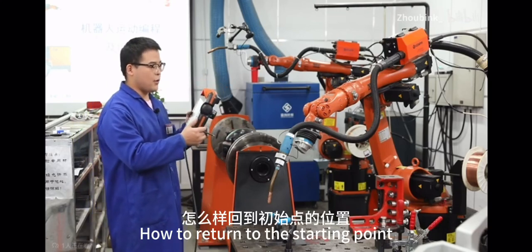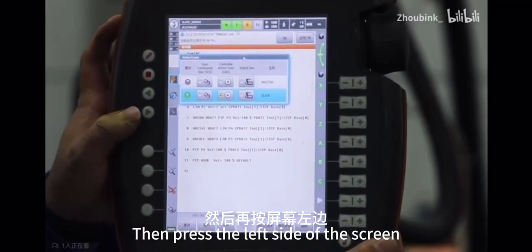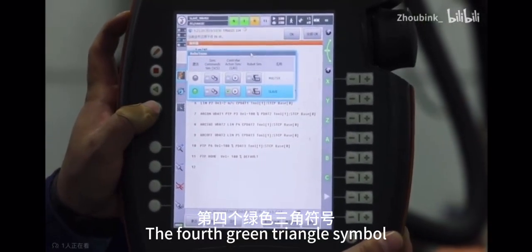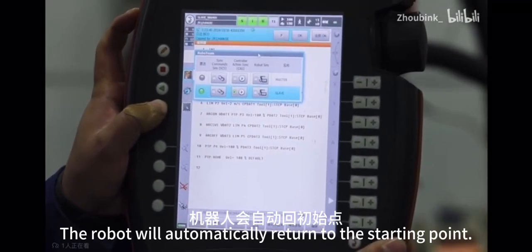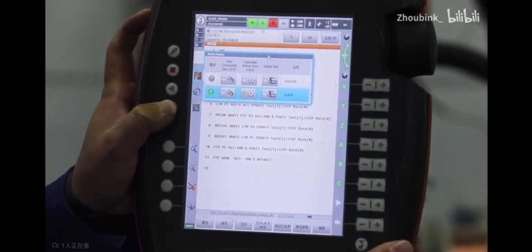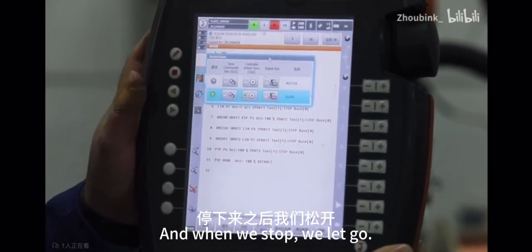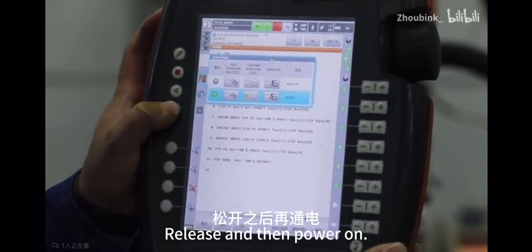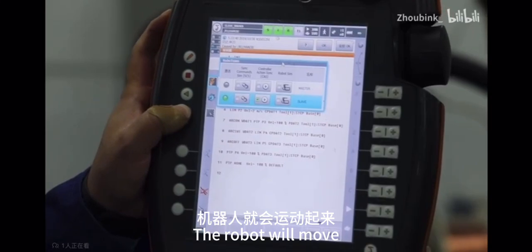How to return to the starting point? Press the power button first. Then press the green triangle symbol on the left side of the screen. Keep pressing it. This is the program start button. The robot will automatically return to the starting point. It will automatically stop, and when it stops, we let go. Release and then power on. Keep pressing the start button. The robot will move.